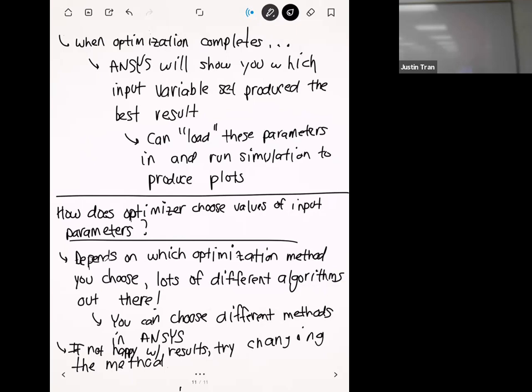The Young's modulus is a measure of how much a material resists deformation. An object with a higher Young's modulus is going to be harder to deform. If it's a material that's been used before, usually the Young's modulus has been calculated, so you can look at a table or search up the material data sheet online. Usually it's one of the first parameters that you see there.